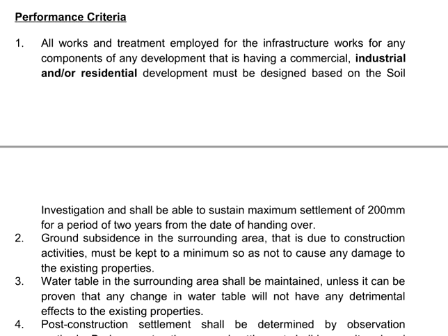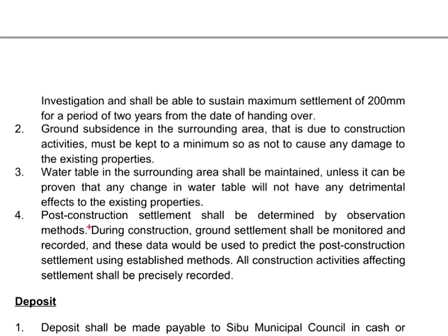Now, as far as the guideline is concerned, we are looking at 200 mm over 2 years from the date of handing over. The post-construction settlement shall be determined by the observation method.